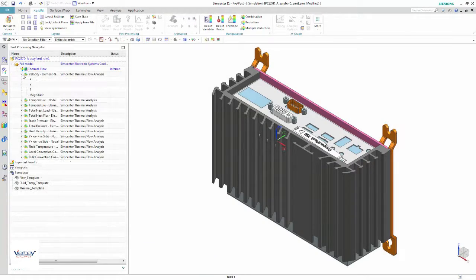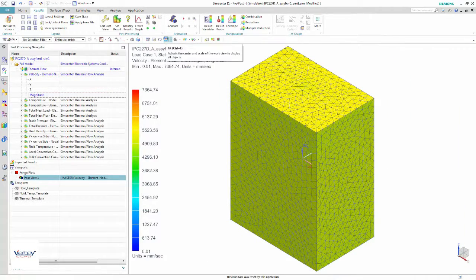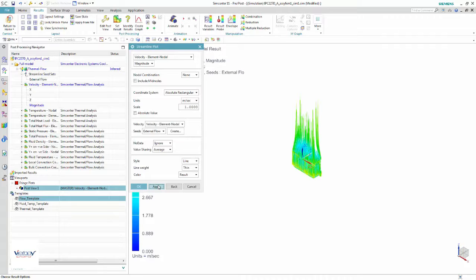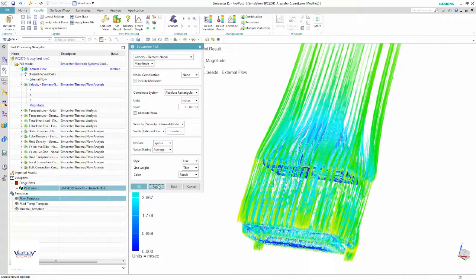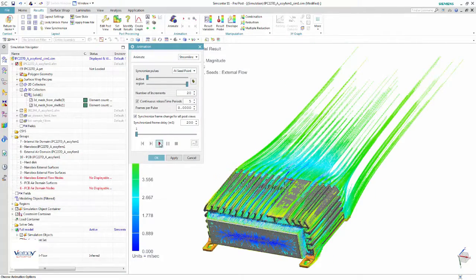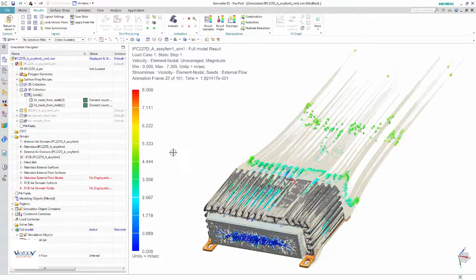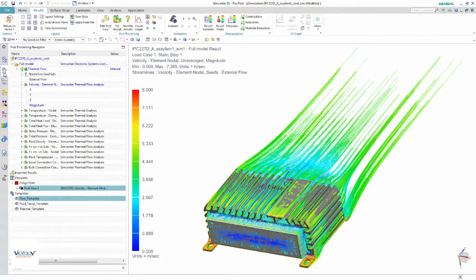Once the model has been solved, we can view the results to see whether this nanobox PC dissipates the heat generated from the PCB, or whether a redesign is warranted. We can first observe that the airflow at the top flat surface of the PC is close to zero, which is expected since the air from the ceiling hits the top of the PC. This is also a good sanity check of our model. Then we observe that the air accelerates along its fins to the side.